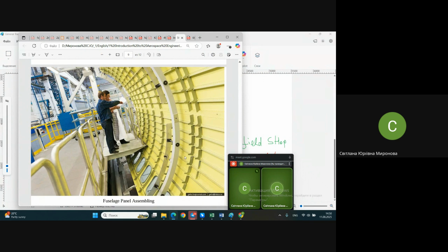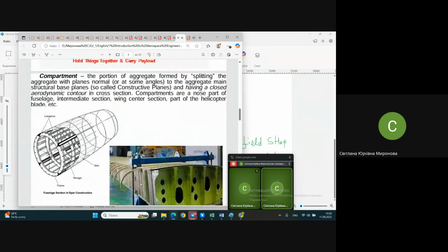But if you're working already since the beginning, you already assemble it like the whole cylinder, how do you bring the cylinder to the press, how will you operate with the cylinder, with rivets, which along each stringer, it will be some tens of rivets in one, let it be panel. When it comes to the whole fuselage, it comes to thousands of those rivets already, tens of thousands. And these repeatable actions, which will be repeated by press accurately, with stable quality, you can't fulfill in case you close this compartment since the beginning and try to assemble it like a closed compartment with closed aerodynamical contour.